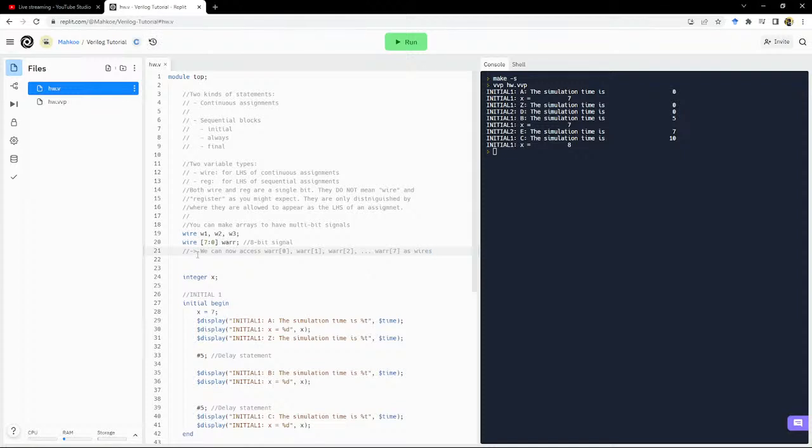Now, at risk of making things complicated, in Verilog, I don't know why, but you are allowed to do something like 0 up to 7. Or you could do 100 up to 107. And those would all make 8-bit signals. In this tutorial, and indeed in pretty much any Verilog you'll ever see someone write in a real context, they will always do uppermost index down to 0.